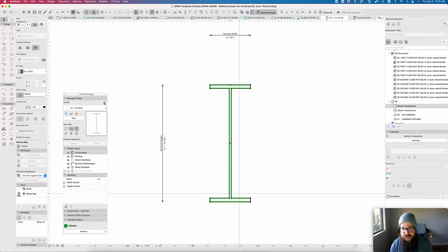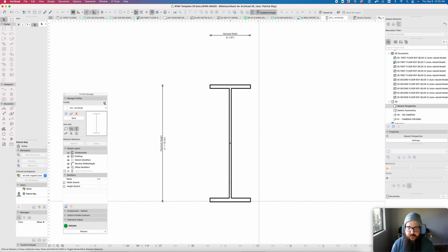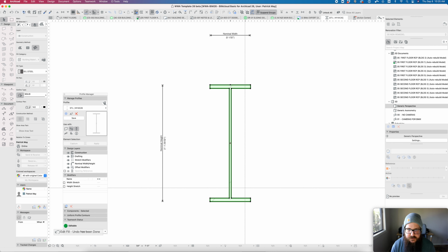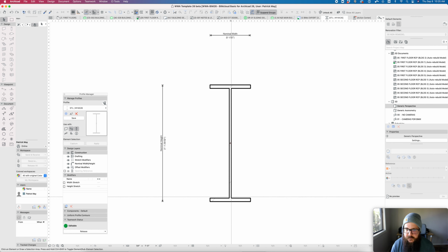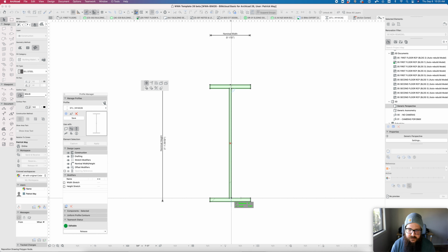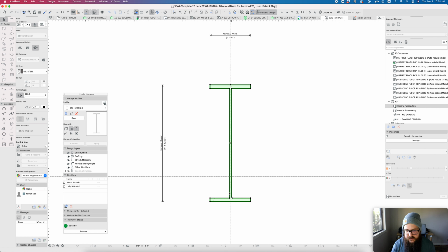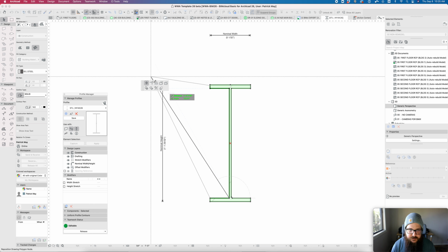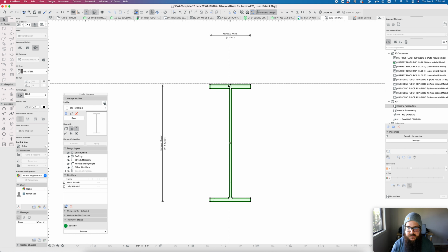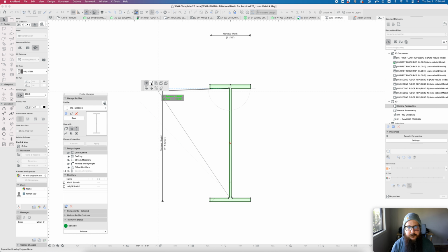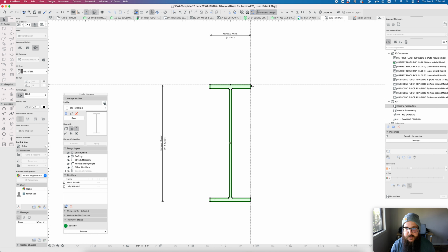If you are going to adjust this profile, always adjust big. It's better to have it bigger than it's going to be than smaller, so we know that we've got more room than less. But generally speaking, as long as we're careful about what we're dimensioning to, this is a pretty precise profile. It doesn't usually include things like the coping where these are connected, so if you did need that extra little bit that often shows up in steel profiles, you may need to add that in here as well, because they are dumbed down, trying to make it ideal for polygon management and not level of detail.